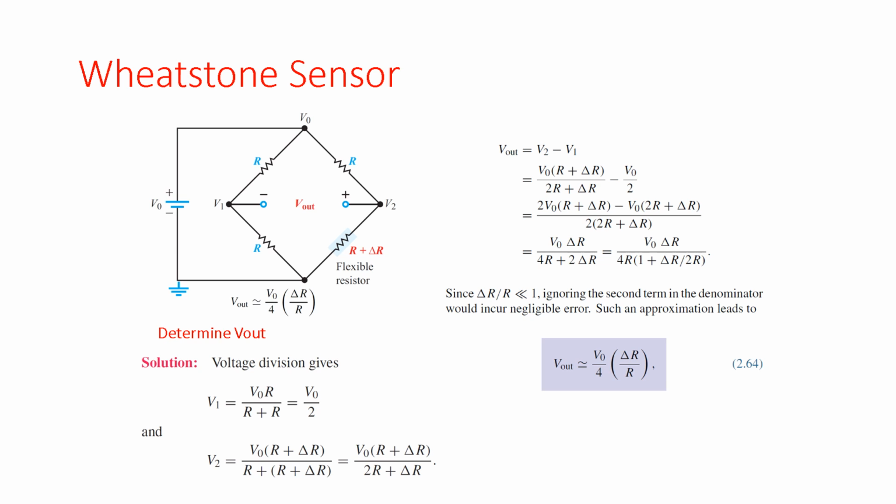That potential difference, or V out, that we solve for here is going to show you exactly what the resistance or the change in resistance is, if you know that. So it allows you to solve the system of equations. So we're going to go through another one of these later on in lab so that you get a more thorough understanding, but this is a really good slide to show if you have essentially three equal resistances, how to calculate either the V out or the change in R if you know the V out.